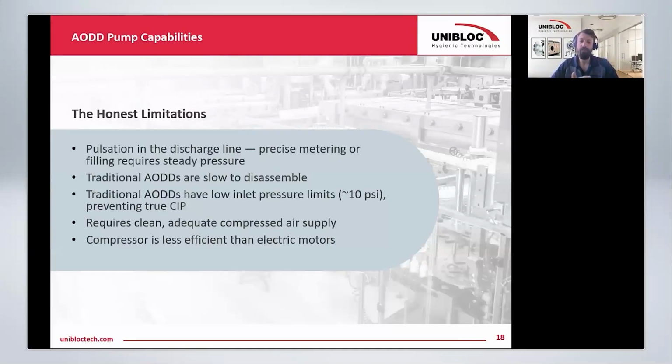Some of your conventional style AODDs with the pipework manifolds can be time consuming to maintain. Especially on the bolted styles, you can have 20, 30 bolts that you have to take apart just to get to the diaphragms. And that just takes a lot of time, and then you've got a lot of components, so there's just a lot more room for error when putting things back together.